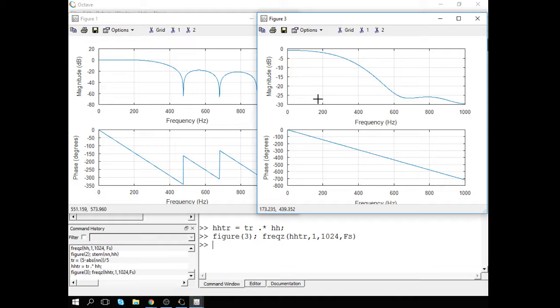If you multiply time, you are then squeezing the frequency space. Yes. Wider here means narrower here. Okay. So that's the last point, what we can do is to make this one wider. So we modify the width and see what happens here. I already know that it gets the transition bandwidth lower.